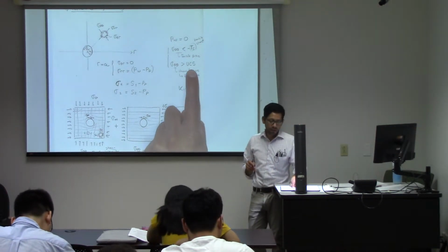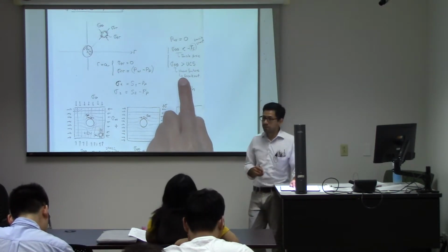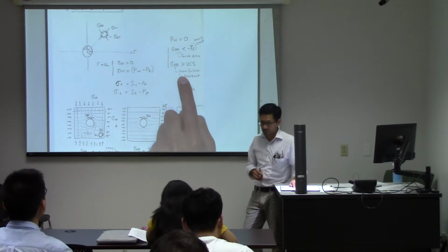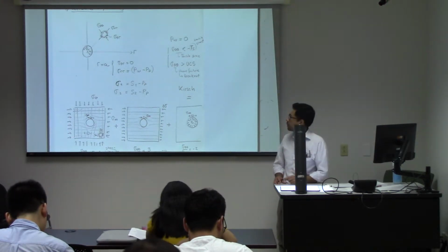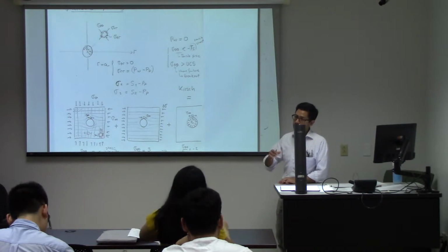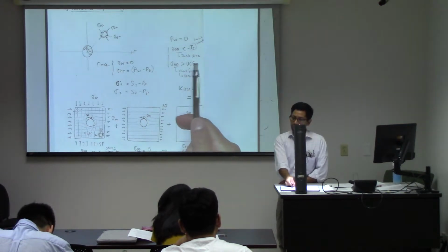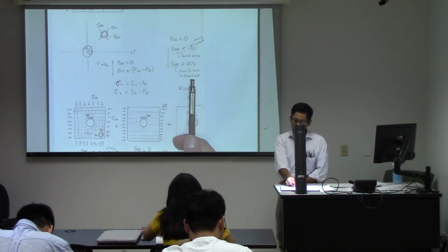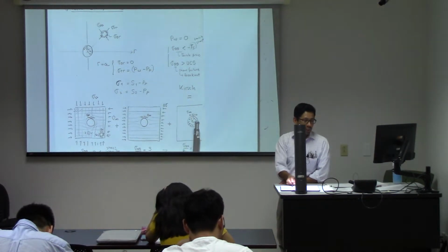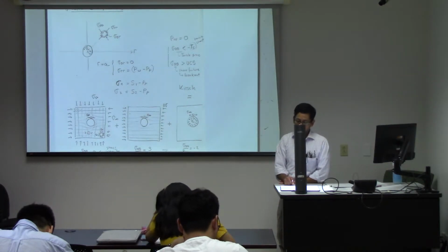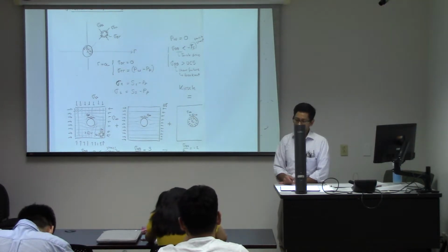And you will say, but if this is compression, why does he call it shear? Okay, we'll get into that later on, okay? But believe me for now that this is a shear failure, and this is the name of the failure type, and it's called a breakout. But just check the hoop stress. If hoop stress goes negative and goes beyond the tensile strength, you will expect to have a tensile fracture. If your hoop stress goes above the unconfined compression strength with no pressure, effective stress on the side of the wellbore, you're going to have failure of the material in shear in that section of the rock.